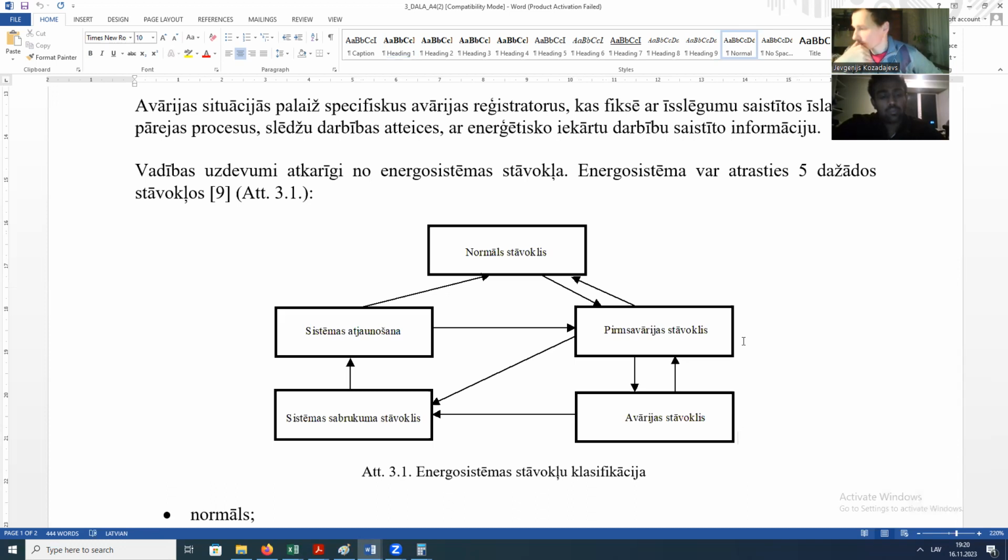What does it mean? We don't have a reliability reserve in this condition, and anything that could happen will automatically lead to a fault regime of a power system. So this pre-fault regime is a very unreliable regime, not a reliable mode. We still are in operation, yes, but everything that will happen could lead to a fault regime.